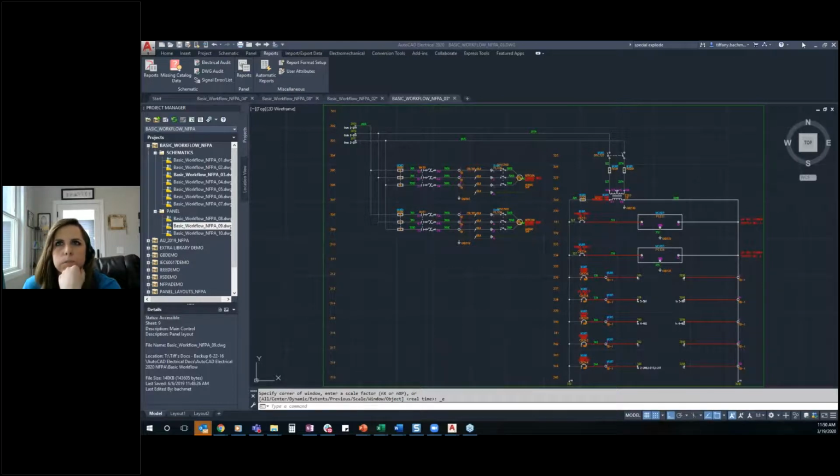What information is that? Is that detection that it's found a duplicate terminal? It doesn't seem like it's based on wire number or terminal strip number or anything like that. It's based off of terminal number and the tag strip associated. That's where it sees duplicates. It's not by wire number, because you could in theory have a new wire number, but have the terminal number be duplicated on it, and so that's where it triggers that.